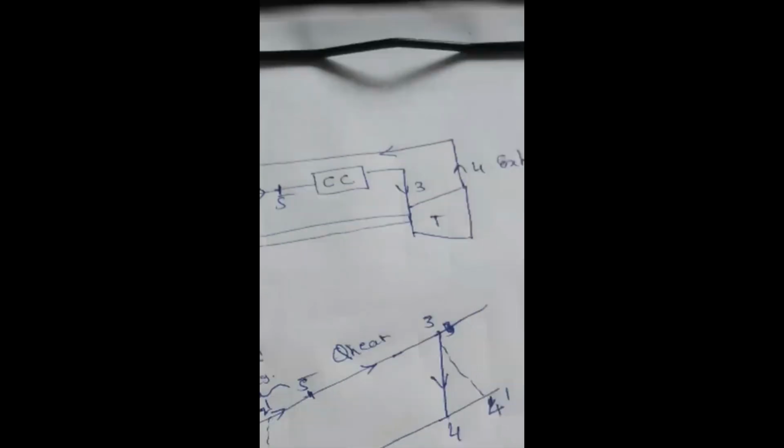Now we are recovering the heat, because point 4 is at a somewhat high temperature. The exhaust is around, say, 60 degrees centigrade for example, and it is transported to this heat exchanger. Regeneration is nothing but a heat exchanger. Point 2 after compression is around 30 degrees centigrade. Now it will come in contact.